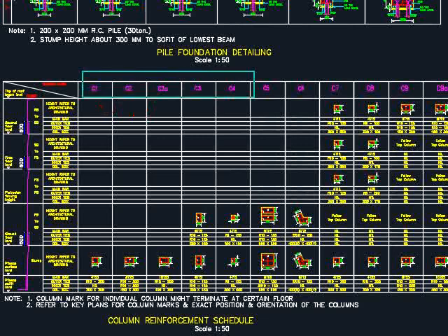First, the number here needs to be in line with the structural key plan at every single story. This needs to be consistent throughout. Remember to provide the name for every single story so that the contractor does not have to flip here and there, searching between different structural key plans in order to know which column it is.